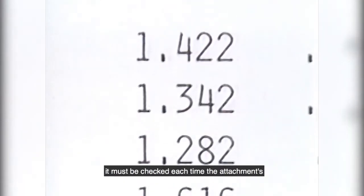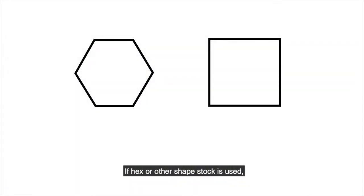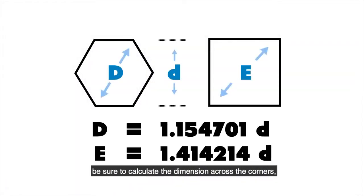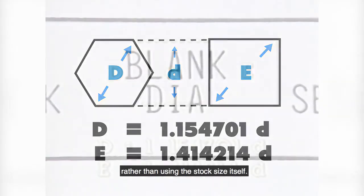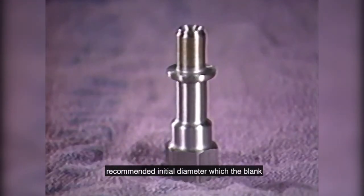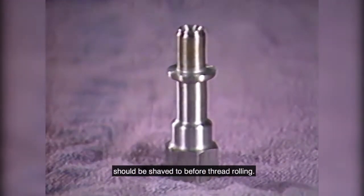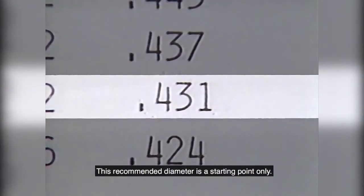Because this dimension varies with each application, it must be checked each time the attachment is set up for a specific application. If hex or other shape stock is used, be sure to calculate the dimension across the corners rather than using the stock size itself. The fifth column, blank diameter, refers to the recommended initial diameter to which the blank should be shaved before thread rolling. This recommended diameter is a starting point only.